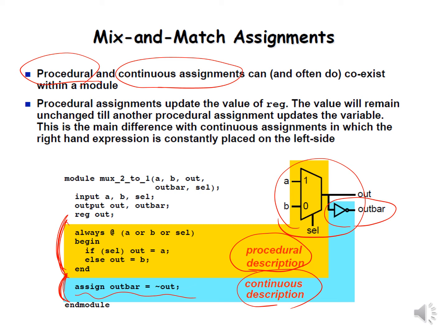Such mixing is totally fine, because Verilog is representing the same hardware. You can describe it either in procedural assignment like always, or continuous assignment like the assign statement.